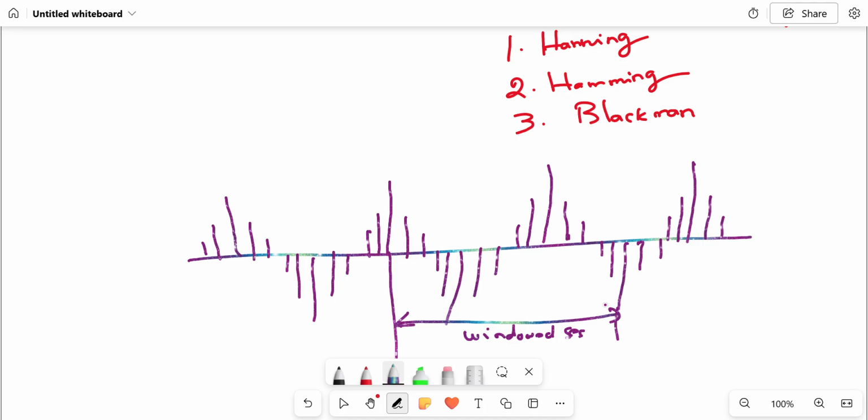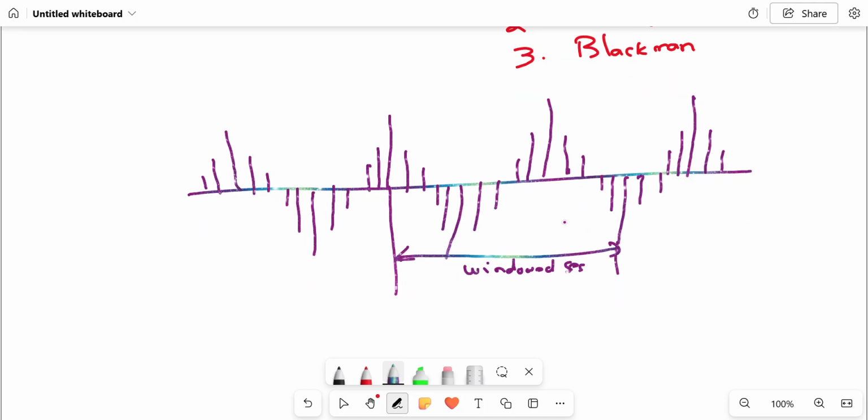Window sequence. If the window width is an integral multiple of periods of all the frequency components of a discrete signal, then the window sequence is identical to the original discrete signal, and the DFT will produce a single spectral coefficient corresponding to each frequency component.